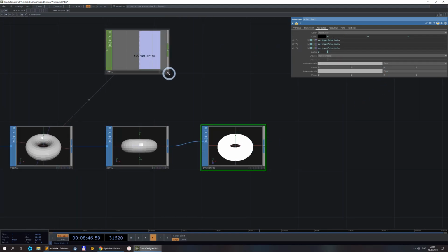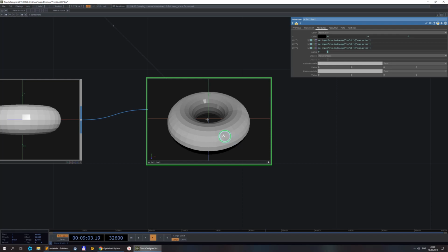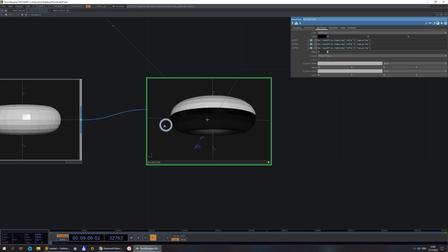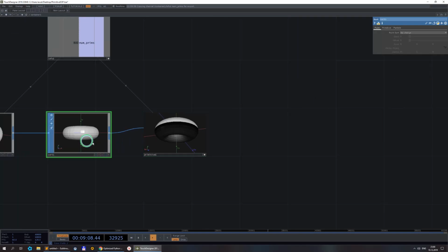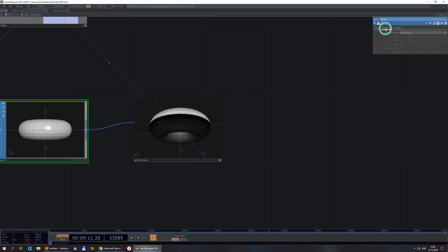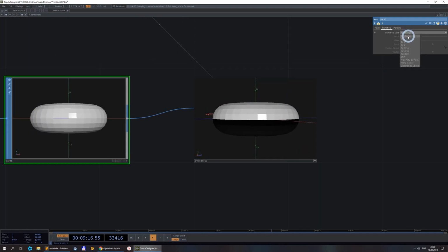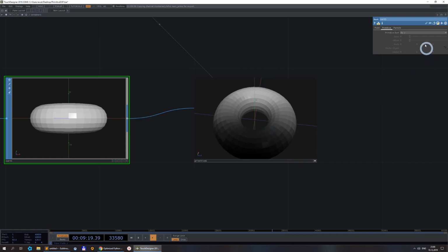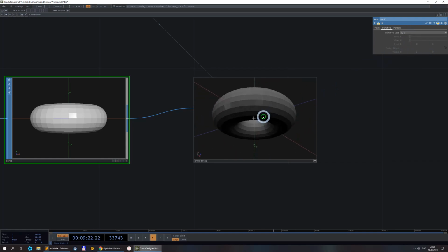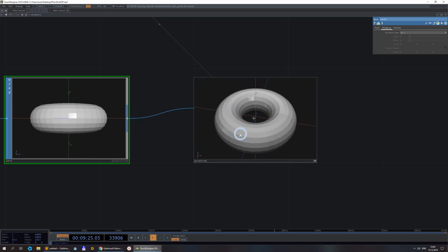So what you can do is you could take an index and divide it by the total number of primitives. And let me copy it everywhere so that it would be uniform color. And now it looks like this. And if you sort not your points, but your primitives differently, you will get a different result. For example, if sorting by X direction or by Y direction, yeah, probably I'll leave it sorting by Y.